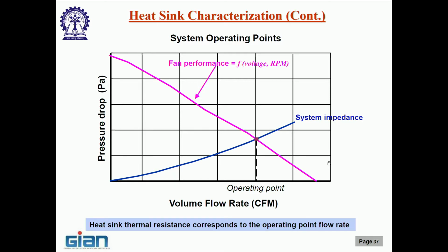Okay. How important is surface finish in the fins? It is important at the next level of detail. People have looked at sandblasted surfaces, dimpled surfaces. So, if you are trying to eke out the next 2%, 3%, 5%, yes, it is important. Where I am going with that is, if you dimple it, you have effectively increased your surface area, but have you also had the boundary layer create more friction, drag?